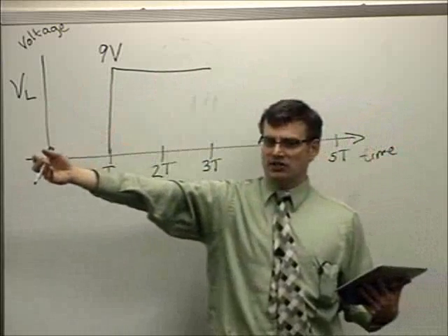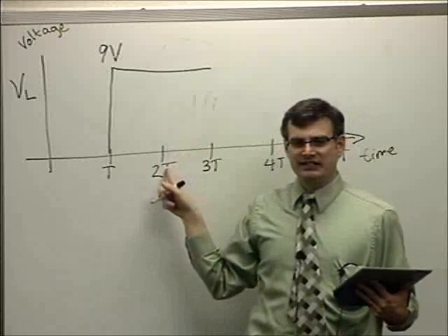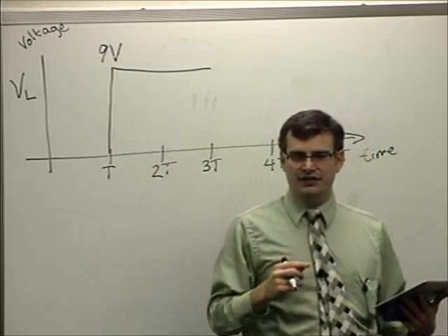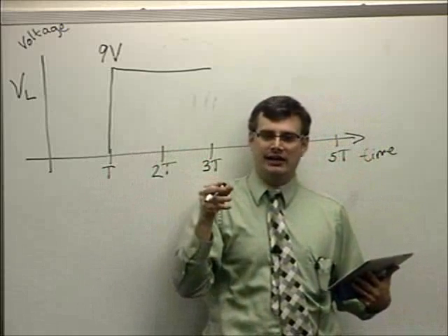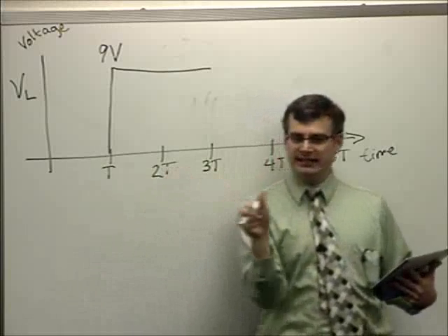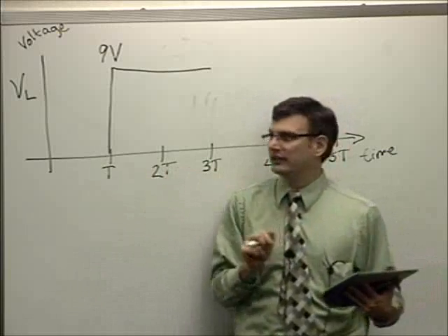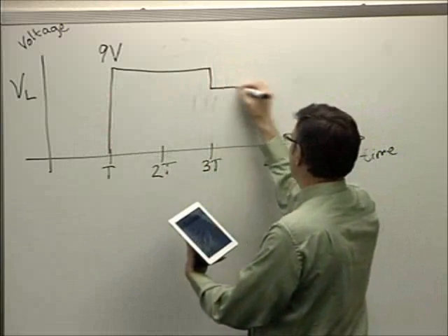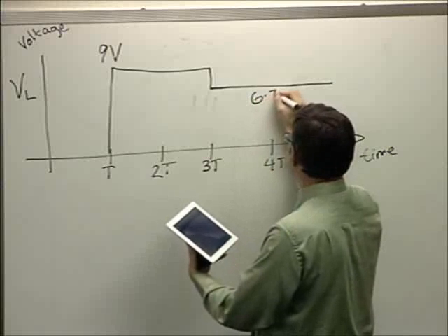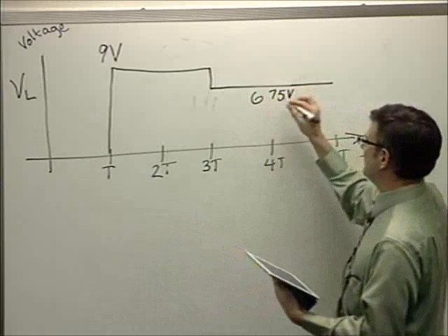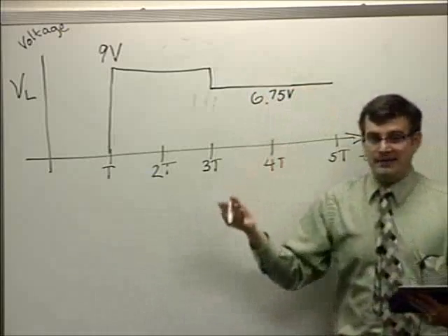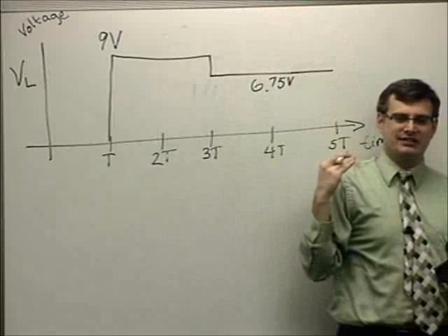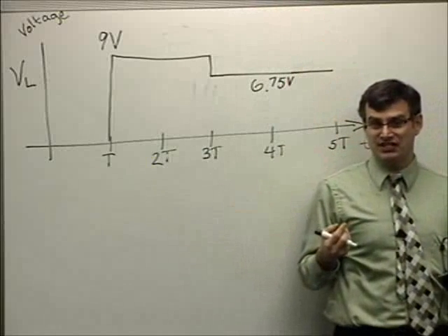When it hits that source at transit time equal to 2, it experiences a negative 1/2 reflection coefficient, which means the waveform that travels down the line is now negative. It's erasing a portion of the total voltage on the line. And so when it gets down and hits the load, this is going to jump down to a value of 6.75 volts. And that value is going to persist for 2 more transit times. Why? Because there's going to be a reflection back to the source side, and it's going to have to reflect back to the load side before we see any more changes in the system.